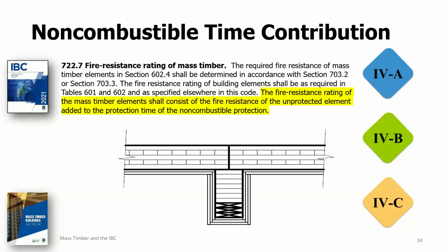Specifically, it not only increases the fire resistance rating of the mass timber elements to which it is applied, but it also prevents or delays involvement of the protected surfaces. This can allow time for the combustible contents, like furnishings, for example, to be consumed and burn out before the protected mass timber ever becomes involved in the fire. And by being involved, that means it's being consumed and contributing to the heat release of the fire.